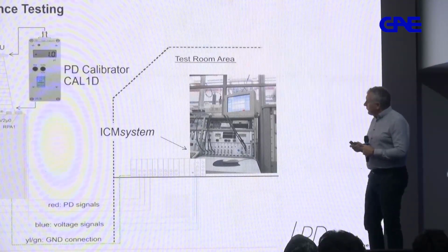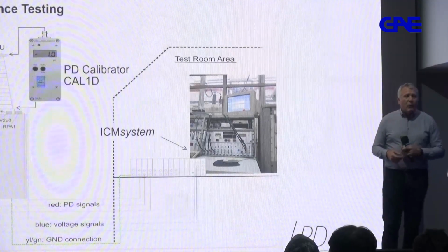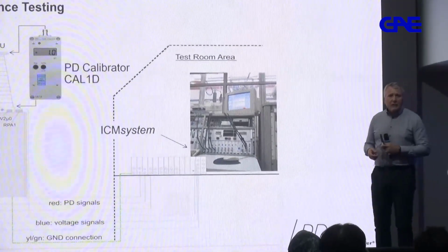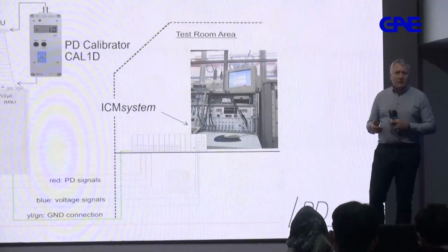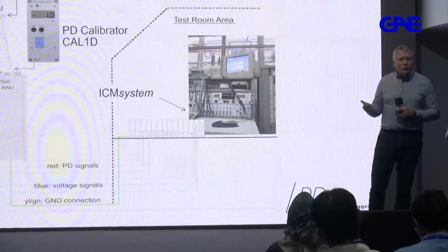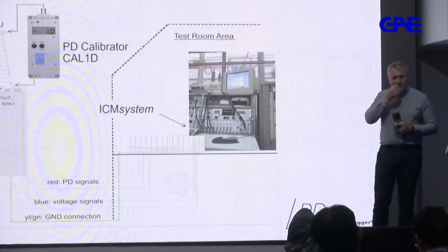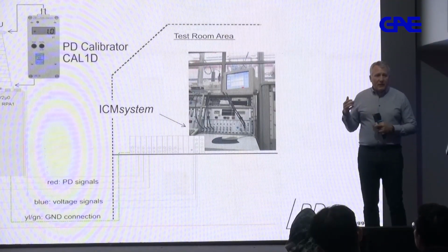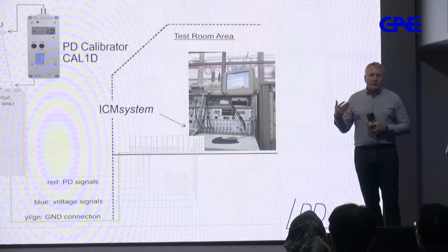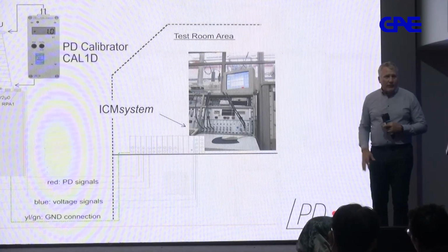Here I'm going to show you, for instance, what's happening inside of any big power transformer factory. You won't believe it, but many factories around the world, for instance, former colleagues from ABB, now Hitachi, about 56 plants in the world, are using precisely this system that is pictured here. To do what? To do partial discharge testing based on a standard called IEC 60270. So this standard specifies the levels and, ultimately, the patterns that are acceptable when a transformer is being produced, when a transformer is being delivered to an end customer.